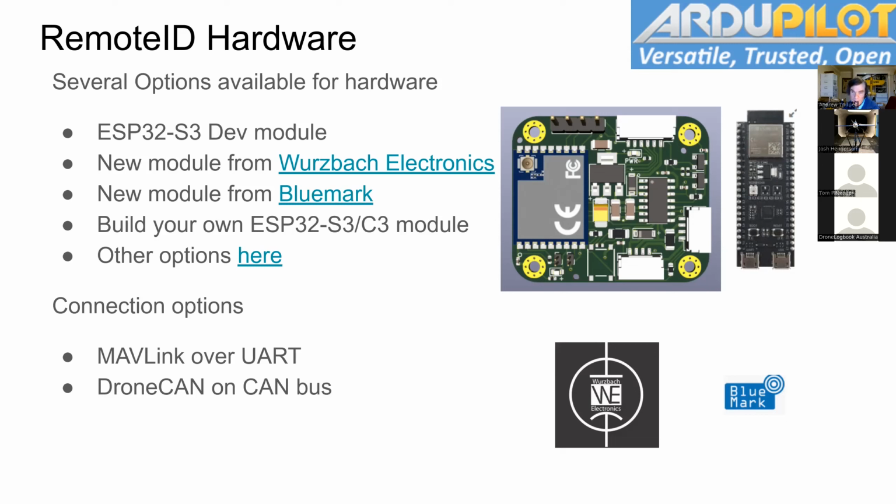You could use a USB serial adapter. I've been testing my device against SITL with a USB serial adapter, and that works. But if you need, I could easily give you a version of the firmware for the remote ID transmitter module that sends the MAVLink directly over one of its two USB ports. It's got a USB UART port and a USB ACM type port.